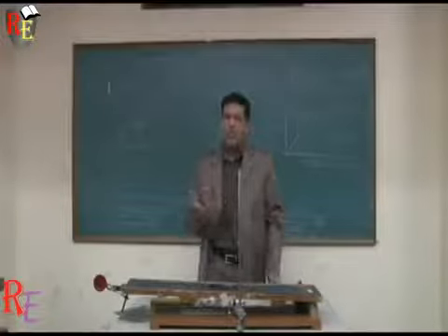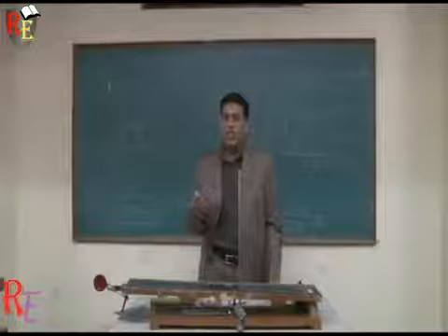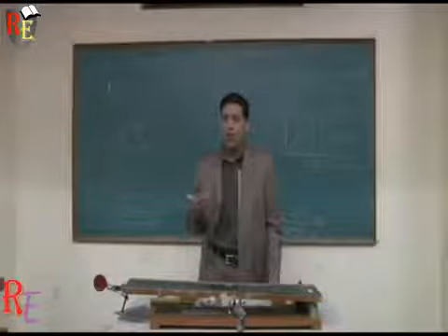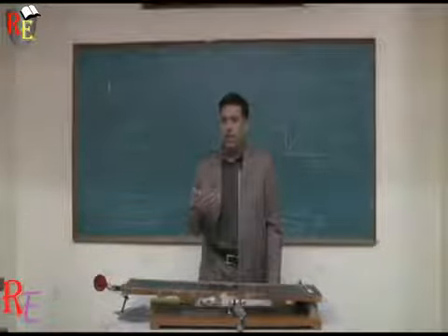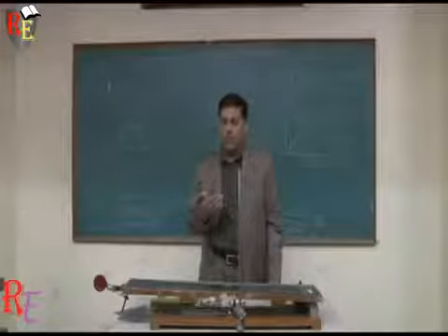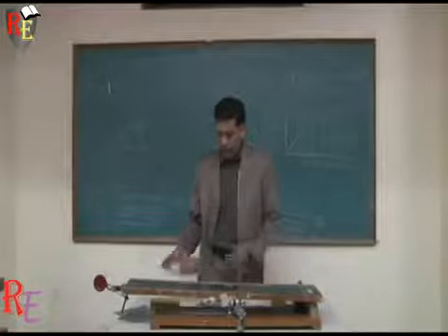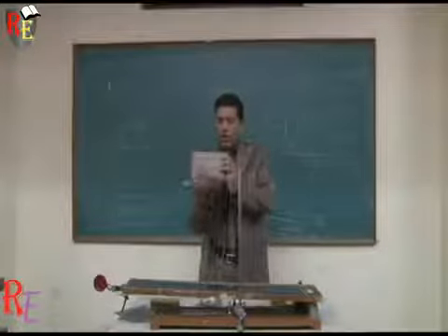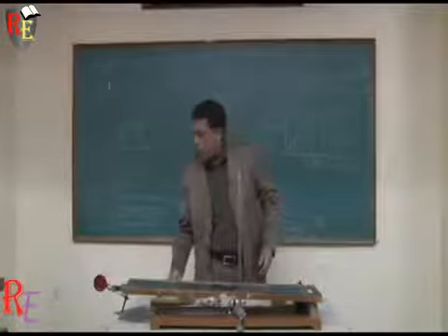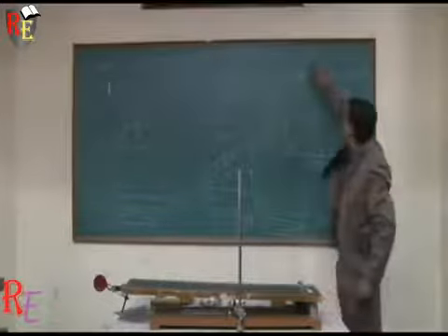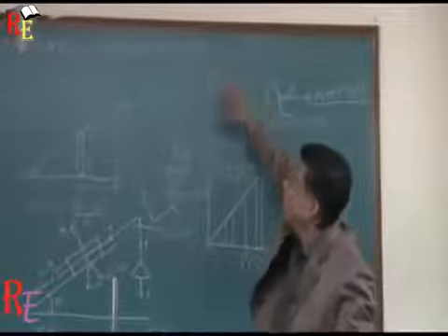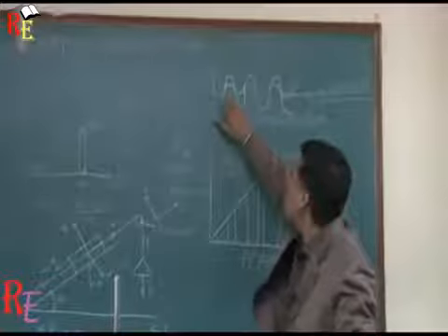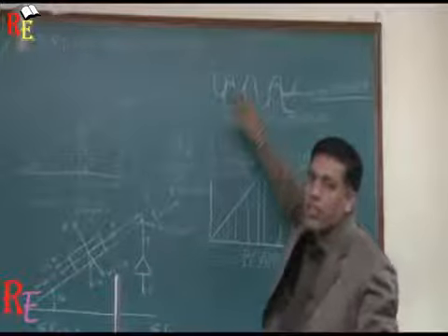First of all, what is friction? Friction is the resistance offered to the motion or the tendency of the motion. Now, the second question is, what causes friction? Every surface has certain asperities, as shown in this figure. When two surfaces come in contact with each other, these asperities get interlocked, and due to this the force of friction is produced.